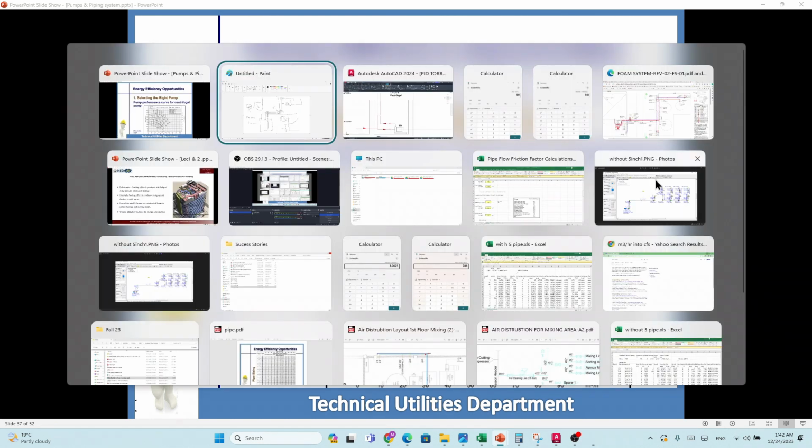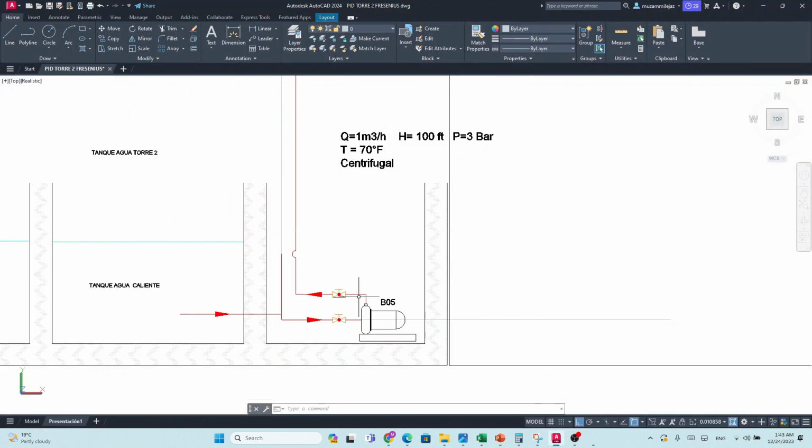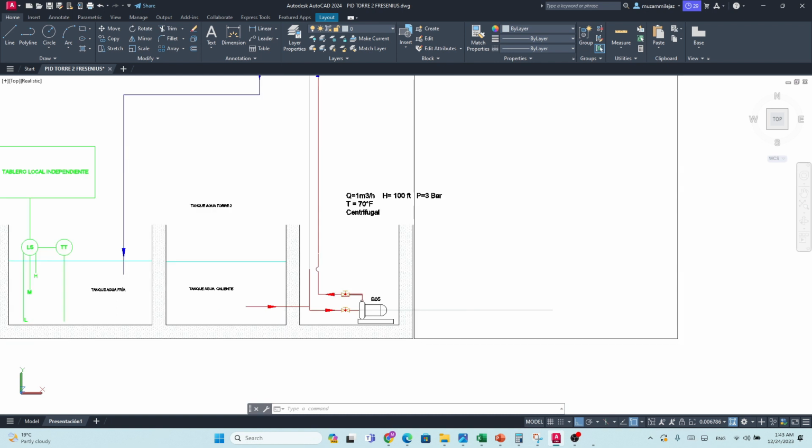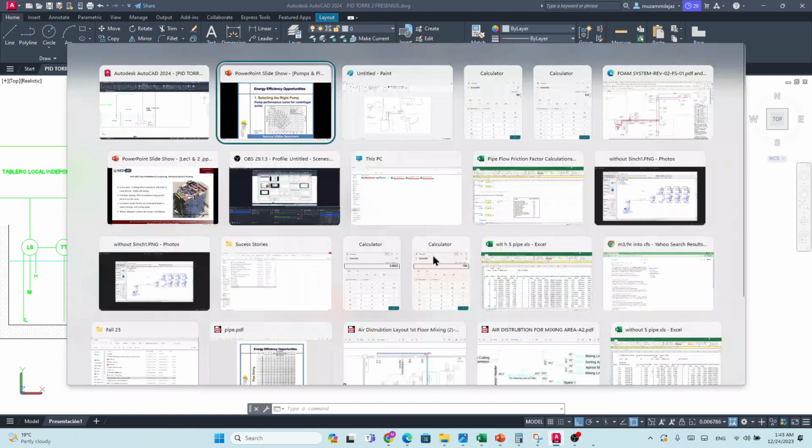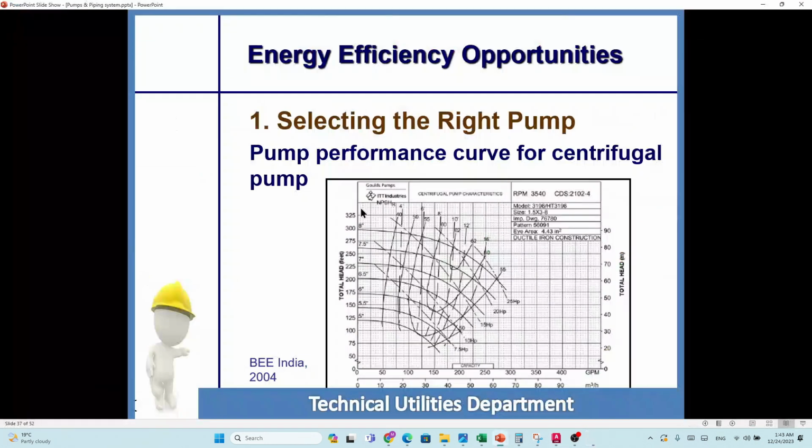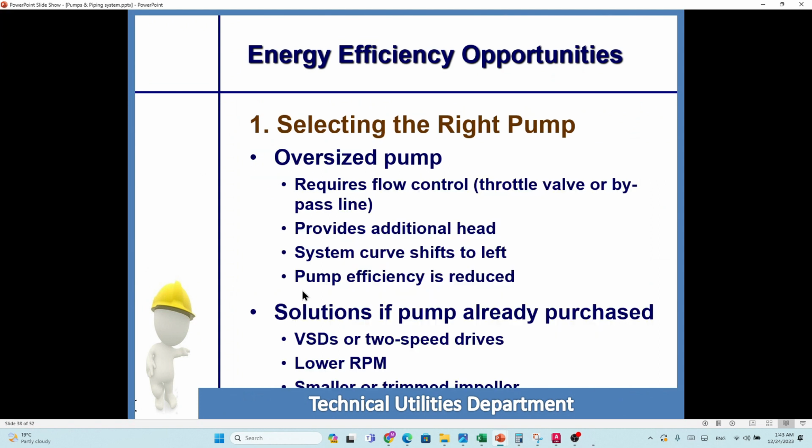Definitely for this system you have to calculate the diameter of a pipe in this way. If you install a larger diameter of pipe, what will happen? The installation cost rises, because you don't need to install a very large pipe. There's no need. But if you install a lesser diameter of pipe, the pump will not flow the water. The pump has some limitation, no? The maximum limitation. For this particular case, let's move towards it later, but first conduct this frictional head. The topic we have,